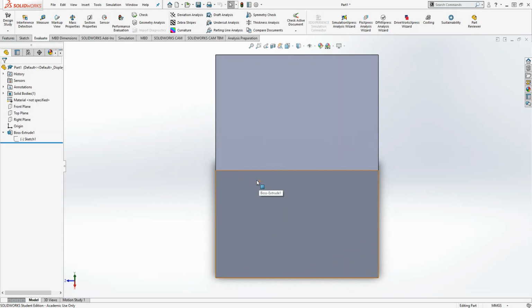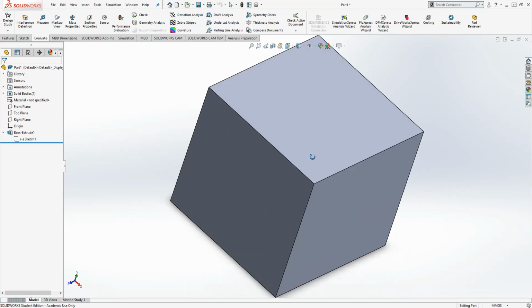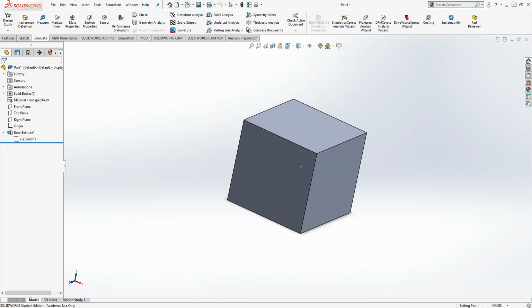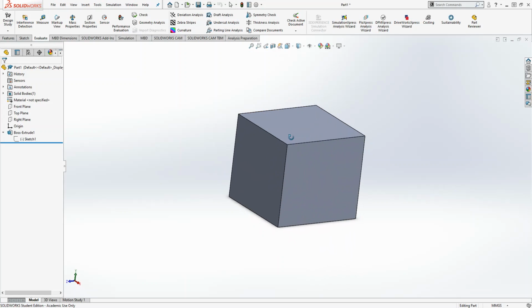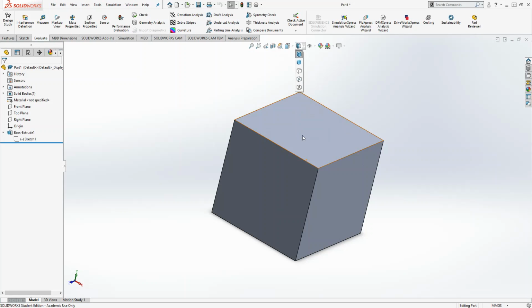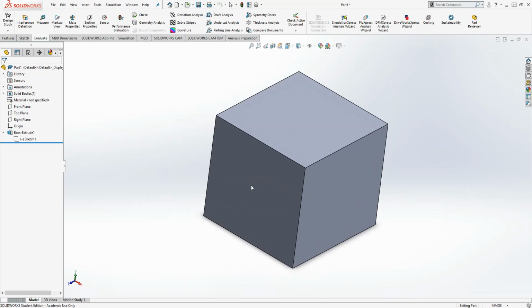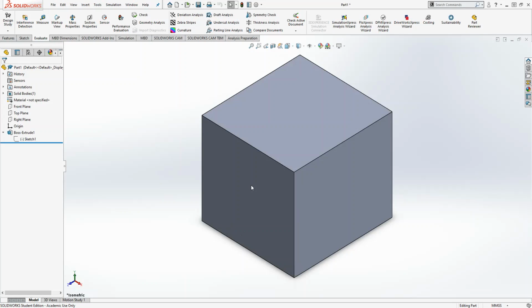Finally, a really great way to move around more in SolidWorks is if you look at this menu, there's a lot of different things like zoom to fit, zoom to area, previous view, selection view, dynamic, all these different items. You have a display style. So if you don't like the shaded edges, you can make it just a normal block part. You can make it hidden lines removed. There's all sorts of crazy little display properties you can do. I'm just going to keep it like this.